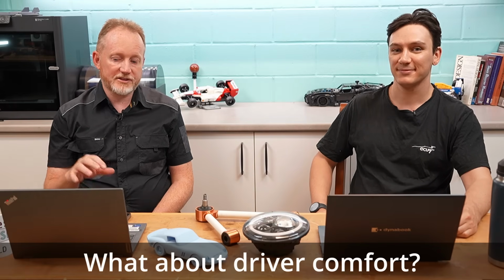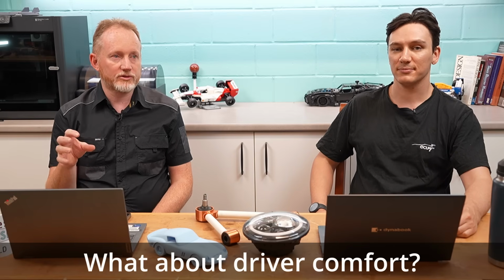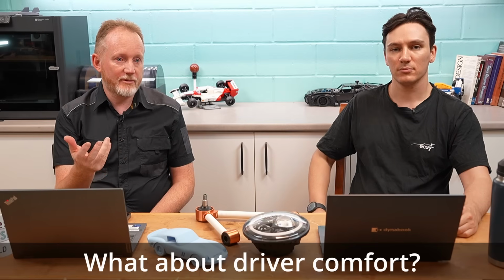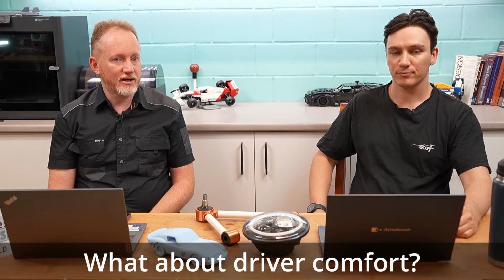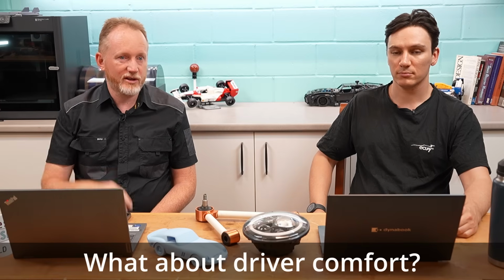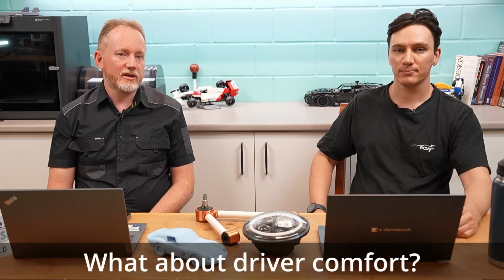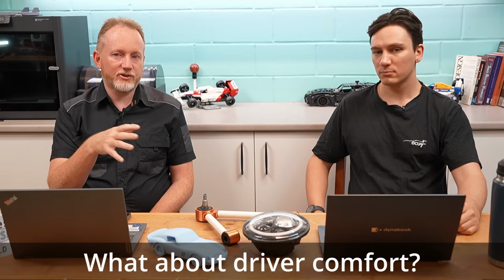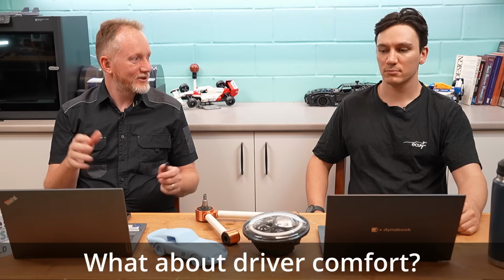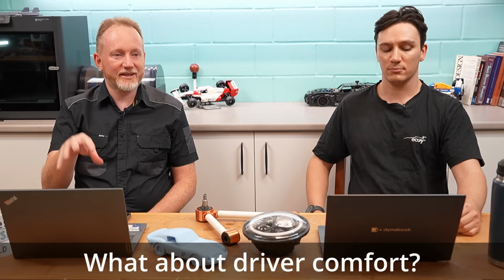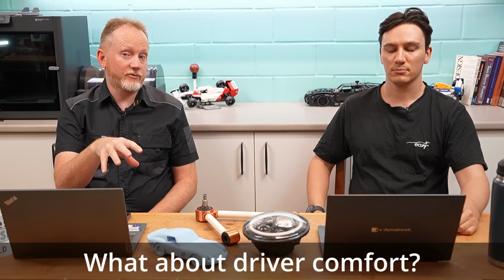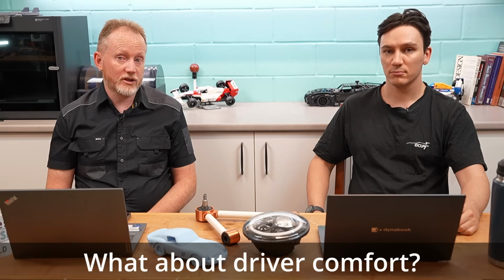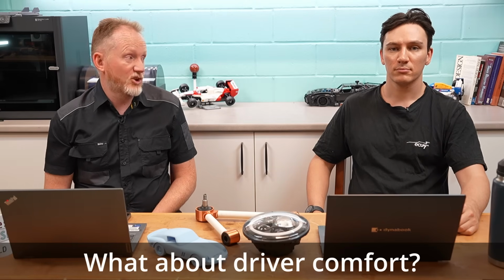Yeah, and I think one of the things that maybe makes some of the CAD models, and the reason we do some of these mock-ups is, we grabbed the driver CAD model off GrabCAD, and I've done a scan of me, and I started building a driver model off that. But the CAD stuff, you're doing it as rigid body dynamics, and the human body actually sort of moves a little bit. So what might look uncomfortable in the CAD is not uncomfortable in the mock-up, and that's why we've been doing the mock-up. It was originally just an ergo mock-up.